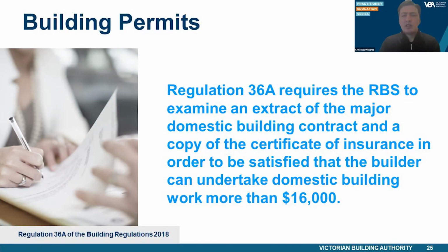Regulation 36A requires the relevant building surveyor to examine an extract of the major domestic building contract and a copy of the certificate of insurance in order to be satisfied the builder can undertake domestic building work. Where the work is not domestic building work, but the cost of work is more than $10,000, the builder is required to be a registered practitioner. They could also be the owner, the architect, or an engineer.